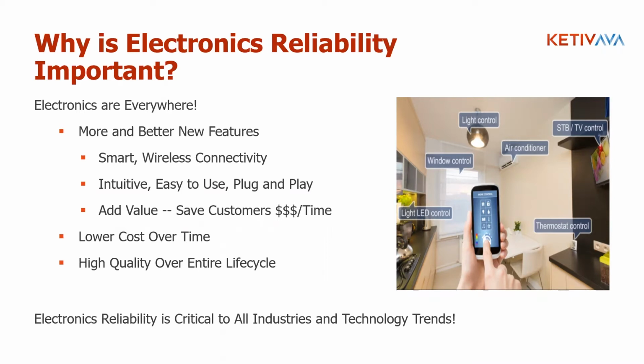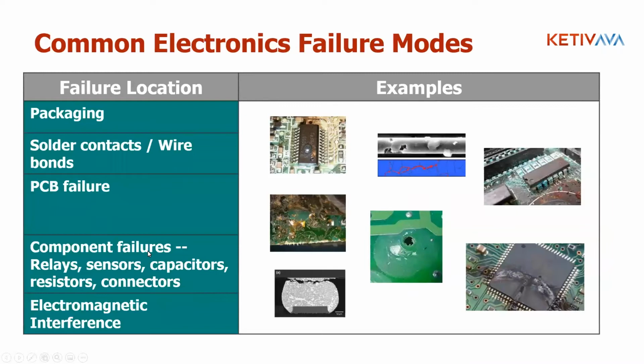And electronic reliability really is part of the universe of producing products. And so we're here to talk about how to improve reliability as we're designing products. And common electronics failure modes are usually due to environmental hazards. We have too much heat or thermal stress, dust, mechanical impact, cracks allowing water ingress, too much current, fatigue, contamination, or transient signals, EM signals interfering with the device.